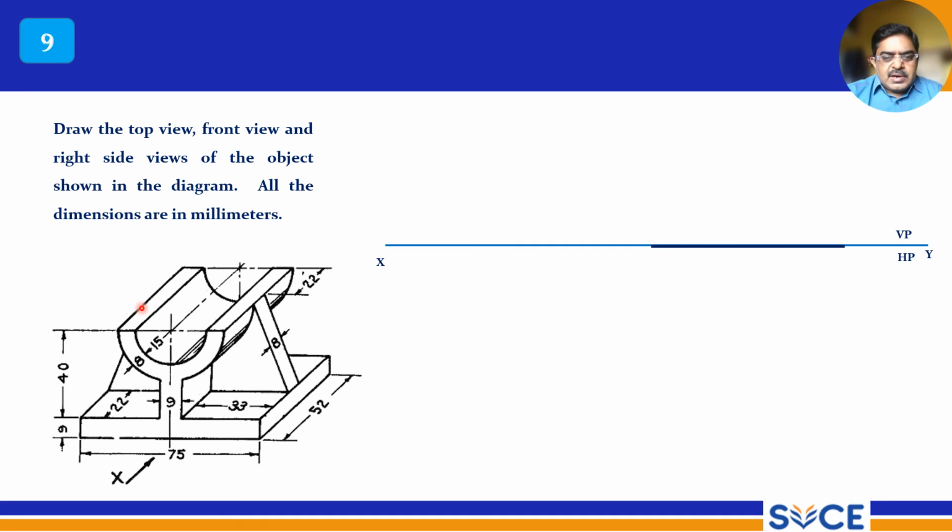So draw 75 mm is the width, and the height is 9 mm, and then you draw a straight line, and then this is 9 mm. So from midline, it is a symmetrical component, right? So you draw a midline and divide 4.5 mm here, and this side 4.5 mm, both way you can do. And now you project it.